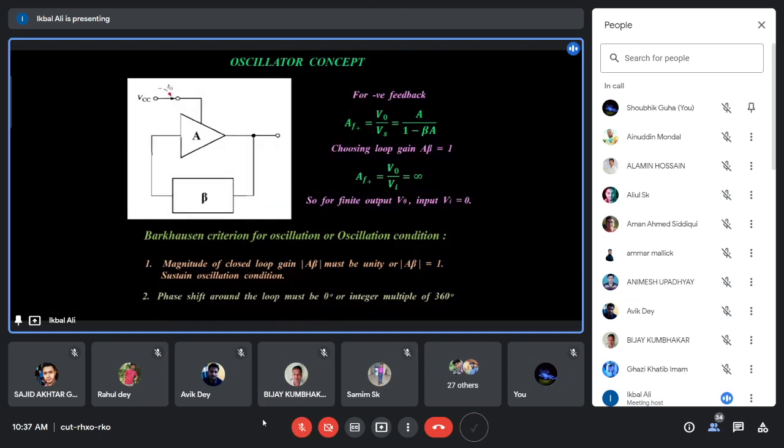Noise is everywhere, okay? You cannot eliminate noise from nature. Everywhere. If you are talking about sound noise, you have sound noise. If you are considering electrical noise, the electron motion is not just a streamline, constant motion. It is not like that. It is a thermal motion. Electron motion is zigzag motion, it can randomly move in any direction. So that actually produces noise in the current.